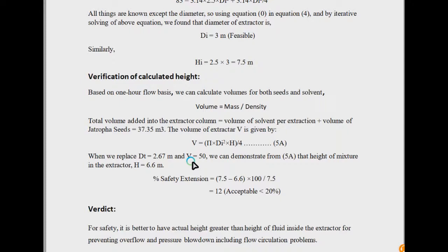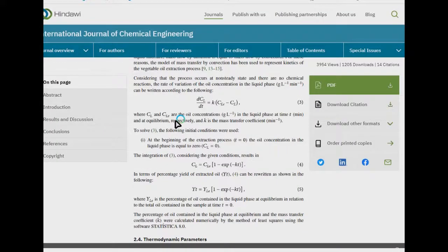But this is not a highly optimized function, because a performance criterion is not involved. It is, however, a reasonable justification to get a contact time and a volume based on it. So this is overall the theme for the design of a solvent extractor or evaporator system for the extraction of any kind of oil from any kind of seed using any kind of solvent.